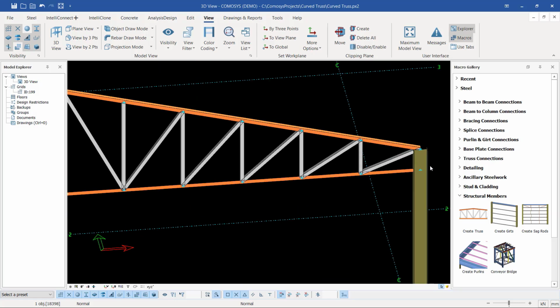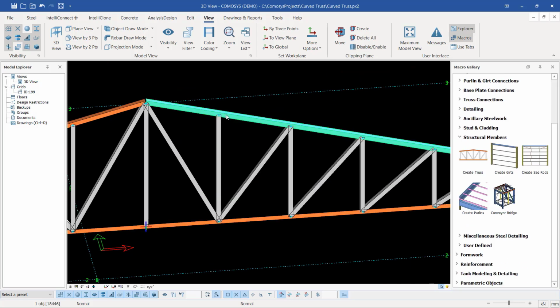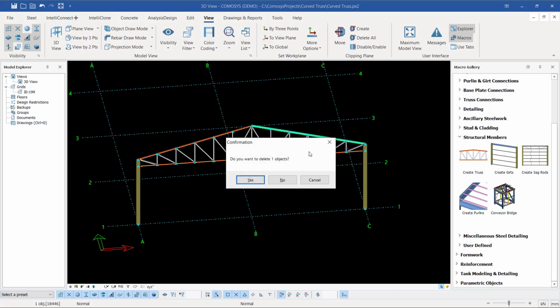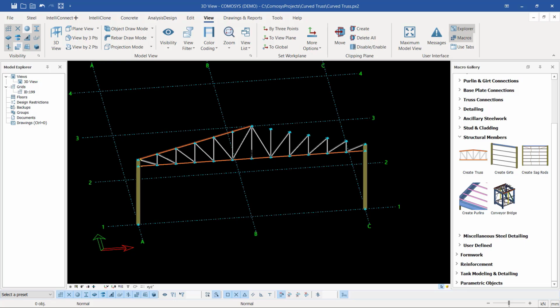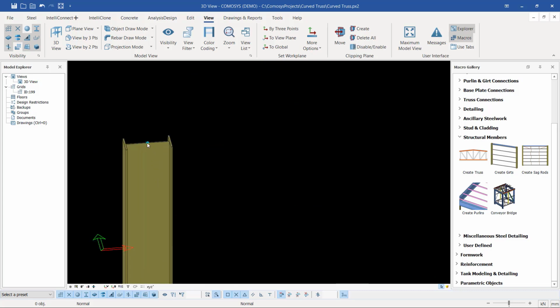So I leave this aside, and also I want to show you how we can create the truss manually. Now, I select this truss here, and let me just select on it and delete. Let me select everything here, then leave only what I want to retain by selecting all, then press Ctrl Shift and select what I don't want to delete. Then I just click delete. So I'll get rid of whatever I don't want to delete.